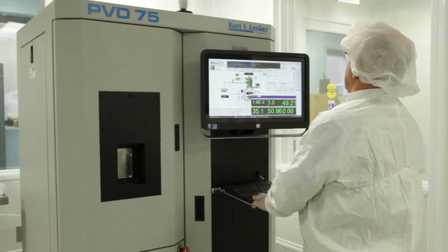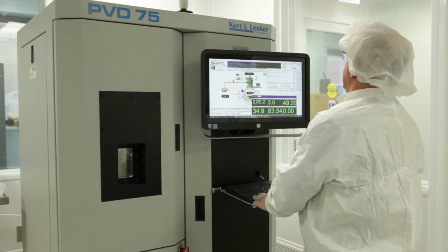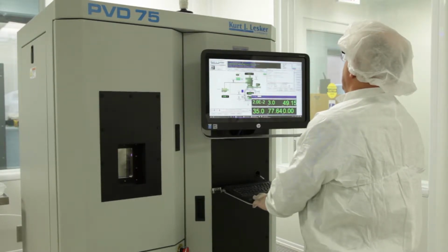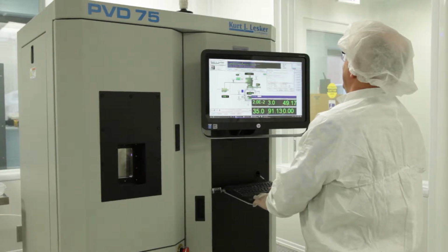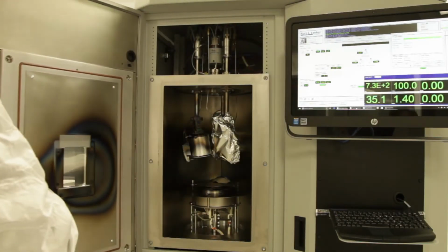This is a sputter deposition tool, which is a type of physical vapor deposition. With sputtering, the material you want to deposit is called a target, which is held within a source. The source and substrate are in a chamber seen through the window on the left. In the system at NanoFabrication Kingston, the source is at the top and the substrate is beneath it.